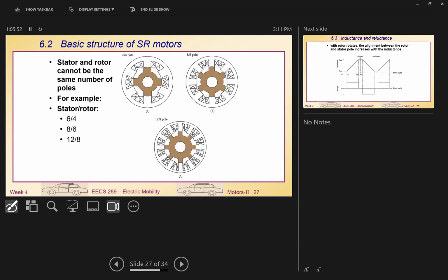So this is how the SR motor looks. The internal part will be our rotor, externally will be our stator. So the windings are here, on the stator. You can see that the internal part is only silicon iron, only iron, without any winding. And then it can rotate. So the magnetic path here, like in this path, or some of them in between, the magnetic field goes through this path. That's our magnetic reluctance.